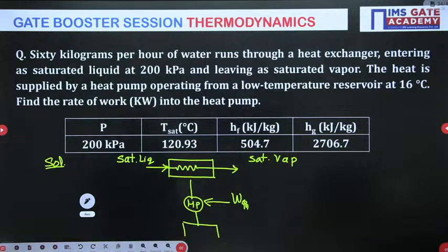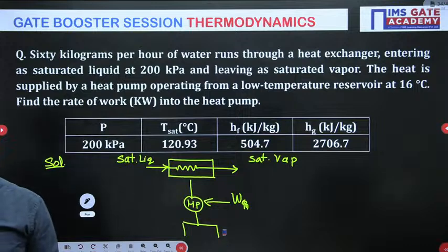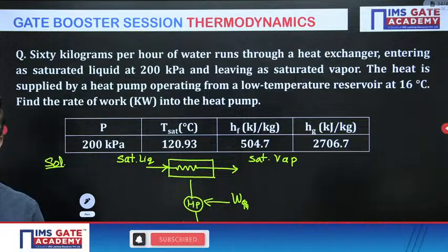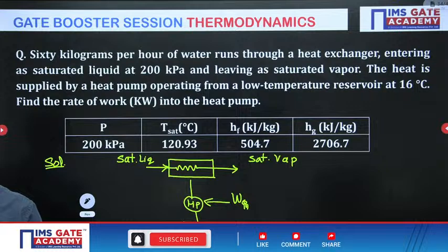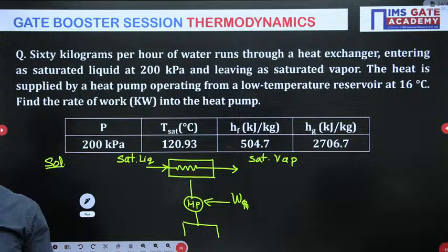No, Aditya, you cannot use MCP. The formula for a constant volume process is, see, how will you write it? MCP ln T2 by T1 will not be used. For a constant pressure process, you will be writing MCP ln T2 by T1.